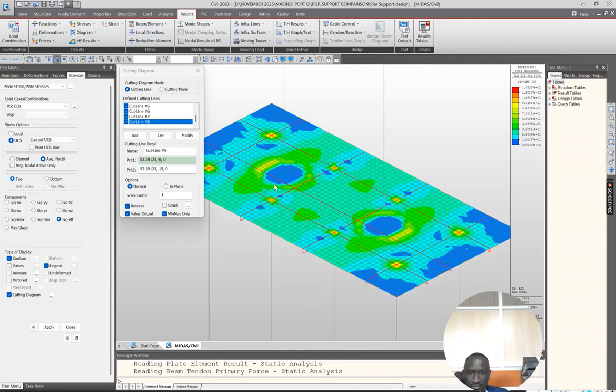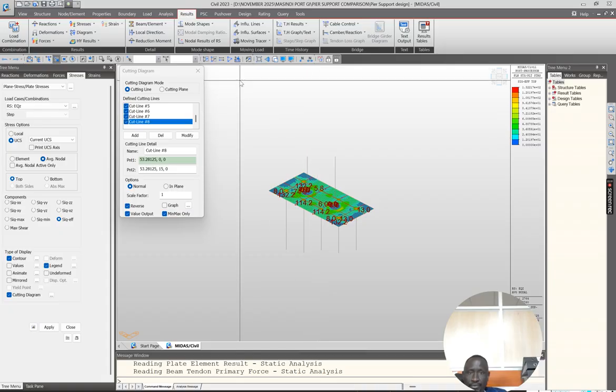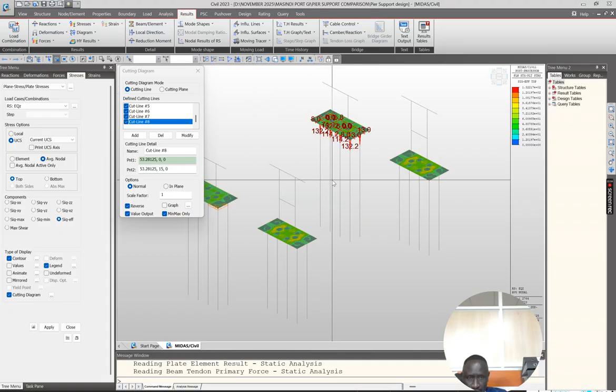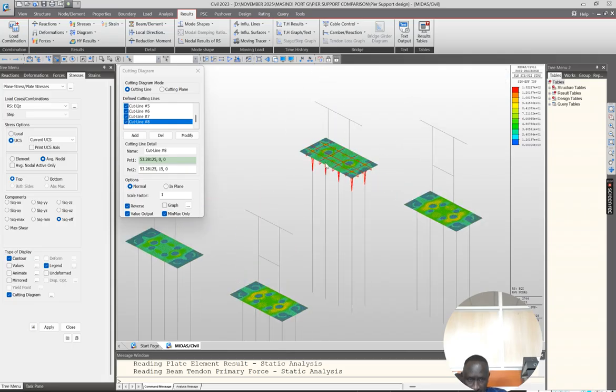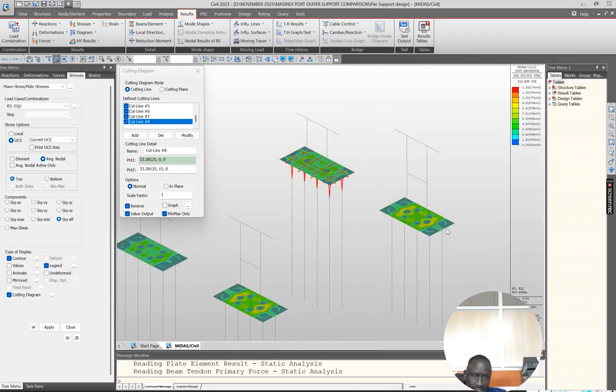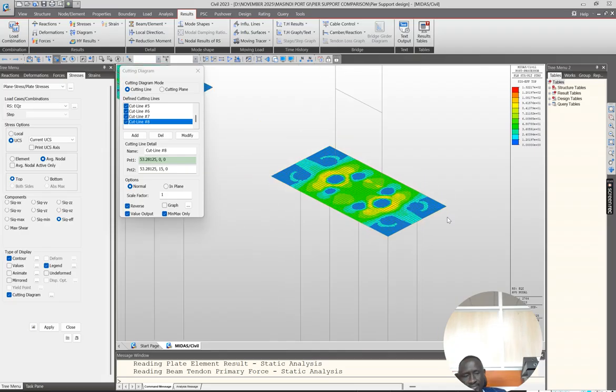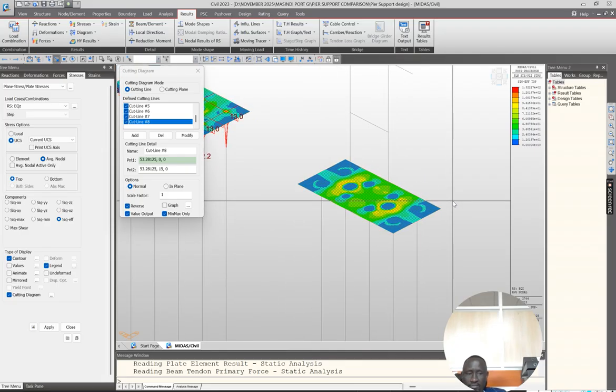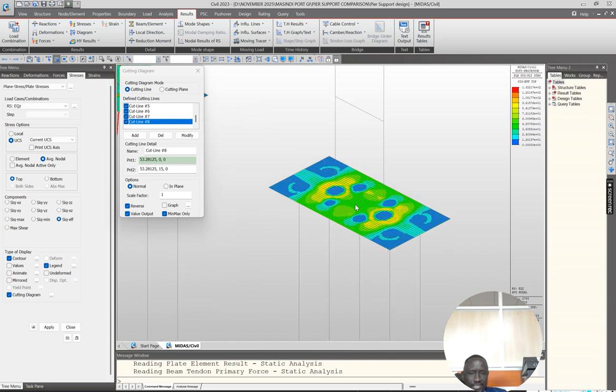That is something that I was trying to look at. It's an assessment to just see the implication of using piles at the riverbed and piles at higher water level. Then I have learned something. Of course, I know there are issues to do with constructability, use of sheet piles. The one down, you need to do sheet pile. If the depth exceeds 5 meters, maybe you need to do double sheet piling. But you have to design and calculate. Then you fill the pile cap with maybe gravel so that you do proper centering and drilling in a way that is safer and correct.